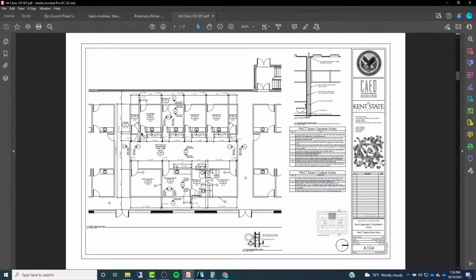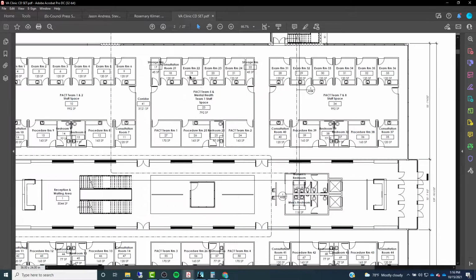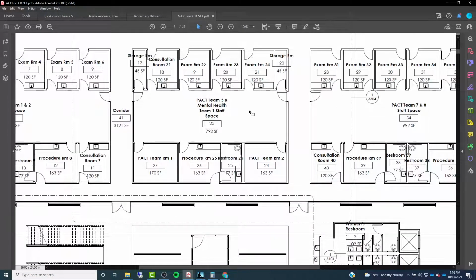And obviously, if we were to go back to our overall plan, imagine trying to cram all of that into this area here at a 1/8 inch scale. There would just be no room for it. There would be so much text all over the place, you wouldn't even be able to read anything. Even at this scale, with certain spaces, it's hard to read things because of overlapping. The tags are all placed as well as they can be, but even so, they're overlapping with the walls, and some of it becomes hard to read. So that's really why we have to use our plan regions or callouts.